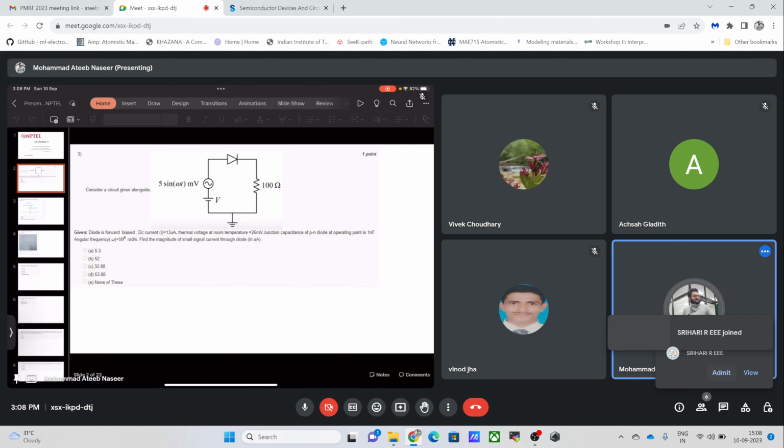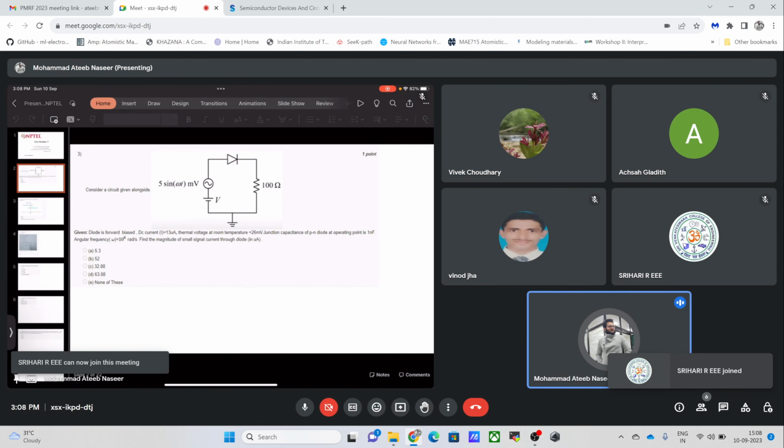This is a small assumption, or small liberty, that we get in the case of homojunction materials, while in the case of heterojunction materials the electric displacement has to be equal. So it has to be epsilon naught 1 times electric field 1 equal to epsilon naught 2 times electric field 2.